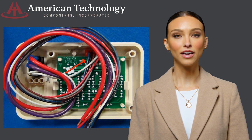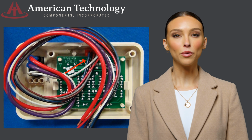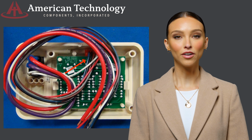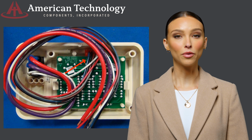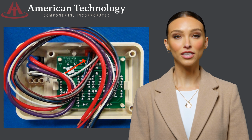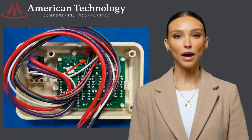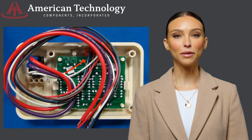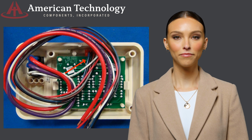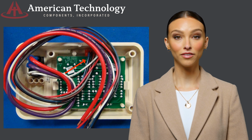In most cases, the color code for the remaining wires will be as follows. In the event that a board is built different, there will be a white sticker on the board explaining the color code of the connector. In this case, after the white will be a gray wire that will attach to the K101 for the gray tank. Next, you will find a brown wire that will attach to the K101 for the black tank. Then you will see a black wire for the gray 2 tank, sometimes referred to as the galley tank. Finally, you see the blue wire that will be attached to the K101 of the freshwater tank.